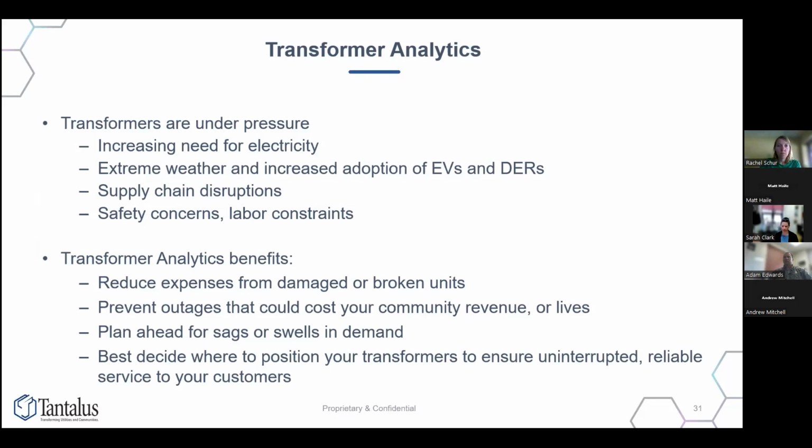If you're looking for alarms at, say, the overview level page based on transformers that are generating, if that number changes, you can get an alarm. If you see so many that are critically overloaded, you can get an alarm sent to the line superintendent. Or if seeing too many event alarms, you can have it sent to the engineering staff to see if there's something going on at the substation. So it's very configurable from that aspect.